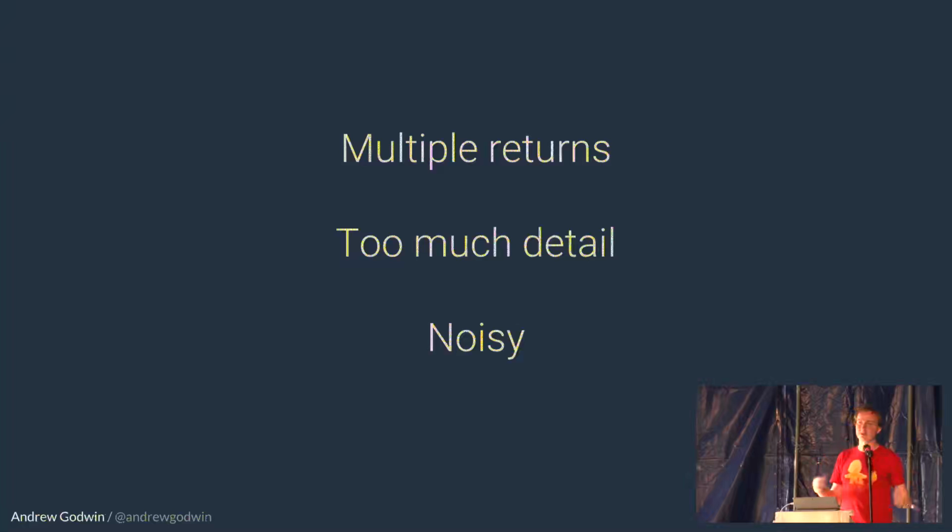If you're trying to make an elevation map, you might get, well, there's the top of a building, but also we went through the glass to the floor below it and got a weak return from that. Or we can see through trees and things like that too. And in general, it's just quite noisy. The data tends to be marred by reflections. Water and steel is especially bad.